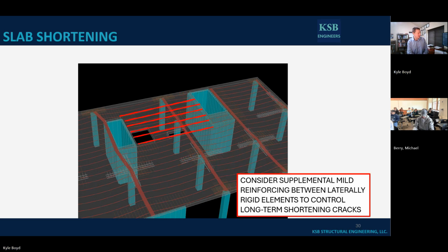That's what happened. All right, now we have 2 concrete cores. Maybe I'll do a pour strip between them like this, so they're not playing tug of war on each other. But eventually, once I place that pour strip back, they're going to be playing tug of war on each other as that slab shrinks, right? It's going to be shrinking in. It's going to be shrinking into its center of area. It's going to want to form some cracks in here.